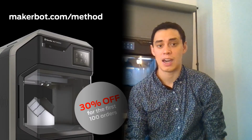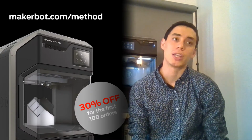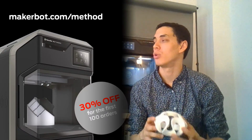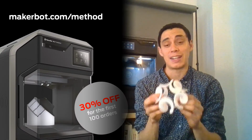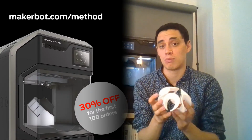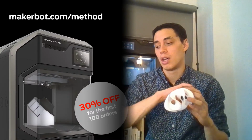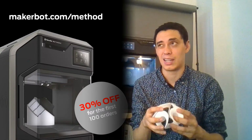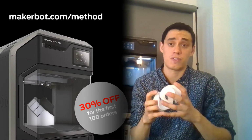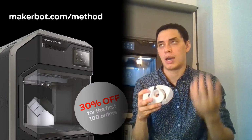What's a polysurface? A polysurface is a surface that's composed of multiple surfaces in Rhino, right? So in the same way that I was saying, once you generate an STL file, the STL is going to be a mesh, and we call a mesh a compendium of triangles that define a shape. A polysurface is going to be a surface that's made out of multiple NURBS surfaces in Rhino, right? You don't use those too much as a concept in other software, but that's the idea, right? It's a surface that actually makes up a more complex object. Well, a sum of different surfaces.